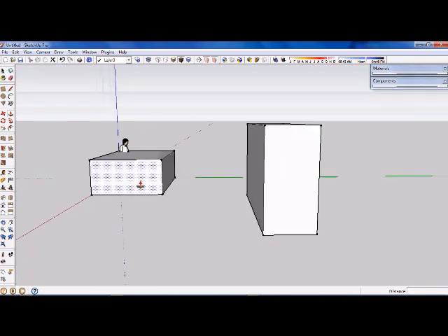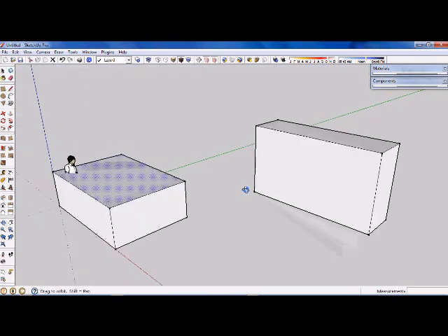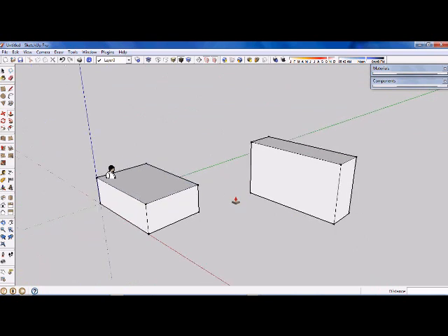So the two options are, as you're dragging you can type the number, then press enter, or you can just do it by eye and drop it, sketch mode, as if you're just roughly positioning it by eye, and then after you've got it positioned you can type the number, press enter, and it'll snap the geometry that you've done by eye back to that accurate dimension. So have a bit of a play with that. We'll pause the video once again.